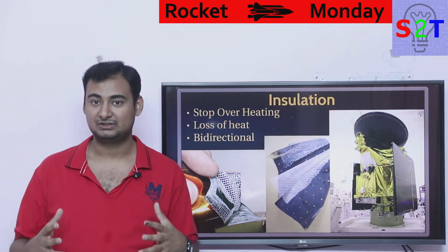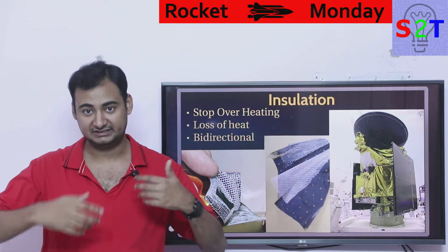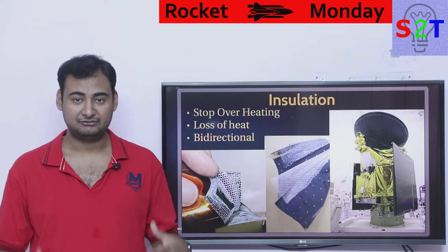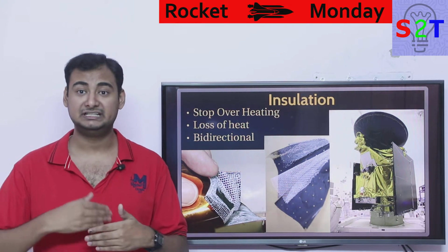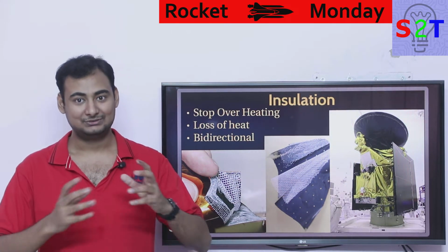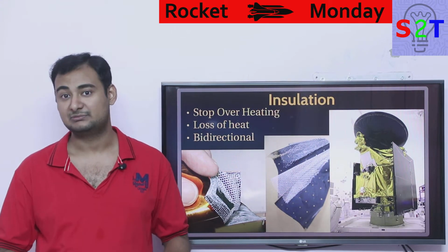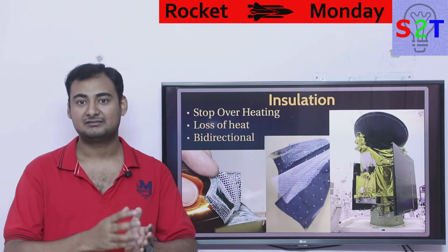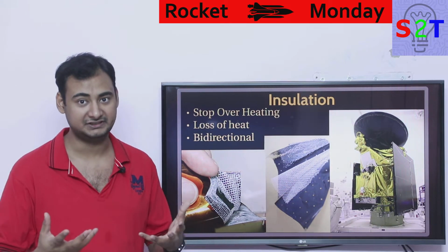And that is why a space suit is built for operation with a human. They have a lot of cooling systems. Basically they have a lot of water circulating to keep the astronaut cool, because an astronaut by default, if not doing anything, like sleeping, will be generating 100 watts of heat. And if your insulator is not leaking that kind of energy, the astronaut will be cooked inside. So you have water circulating, and that water dumps its energy either in another water reservoir, another cooling system, or flat out a thermal bank. Basically, okay, for 5 hours I can absorb the heat, after that you must change me or you're gonna suffocate to death because of heat, not because of carbon dioxide.